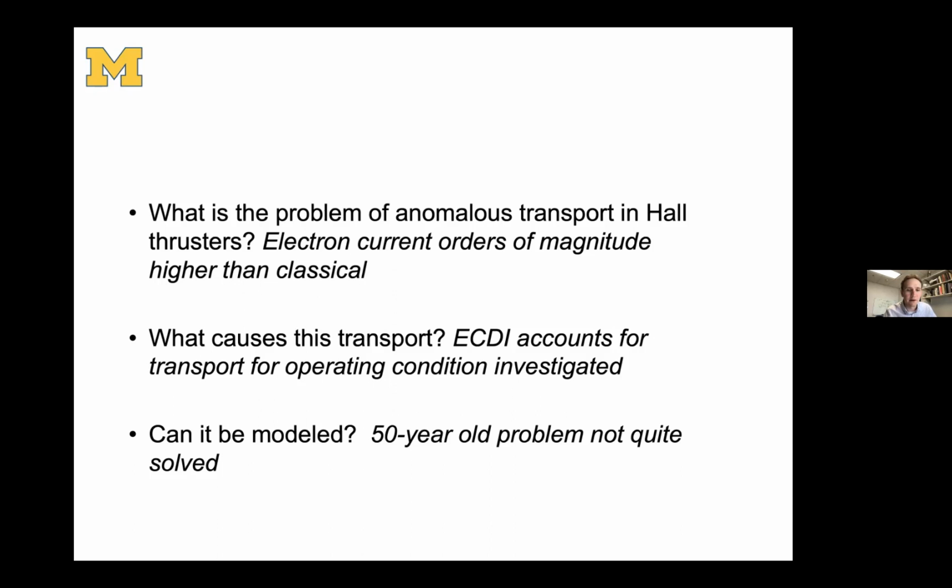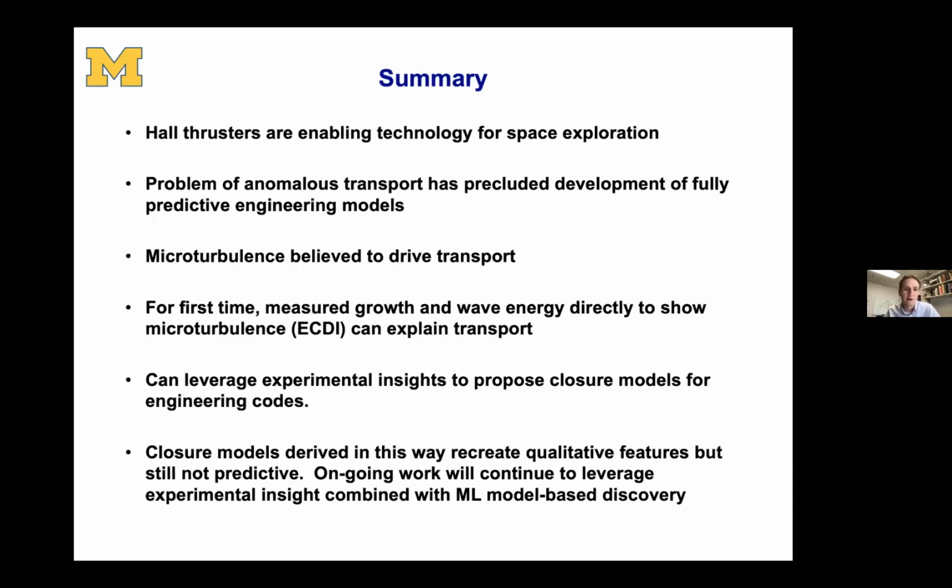But I think we're making good inroads by taking this approach where we leverage experimental insight to inform our models. So to wrap up here, Hall effect thrusters are widely used, but despite that wide use, there are still open questions about how they operate, specifically linked to their electron dynamics. Recent work has seemed to suggest that the existence of turbulence is fundamentally linked to those electron dynamics. And we've been trying to improve that understanding through experimental and modeling-based efforts, with the ultimate goal of developing closure models which are sufficiently high fidelity that we have a measure of predictive capability.